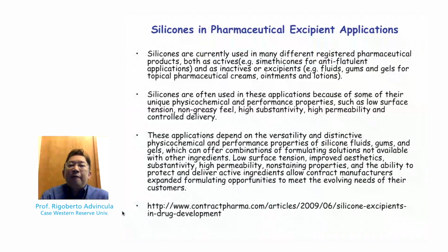Silicones have many uses. They can be used for creams, fluids, ointments. They are used for and take advantage of their chemical resistance or stability against various physico-chemical stresses. They are low Tg, or low glass transition temperature. Therefore, they remain liquid at room temperature. They can be cross-linked to have elastomeric properties. And in fact, they are used as adhesives.